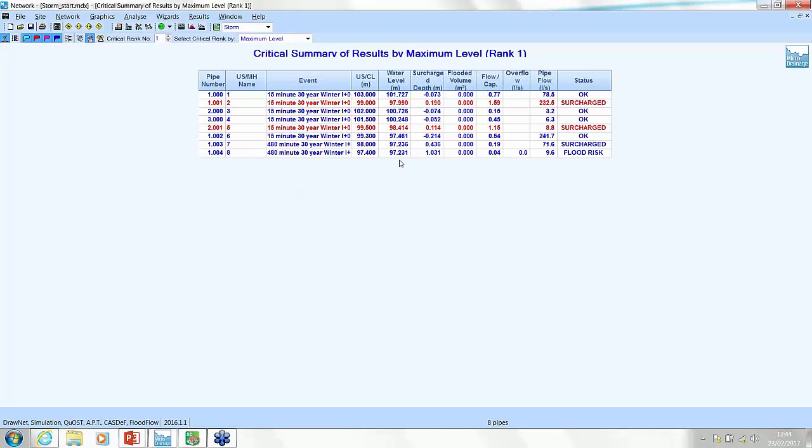So we're going to go with a tank that's 640 meters cubed, side slope of 1 in 4. We can see that the maximum discharge rate into our water course is not exceeded. We're at exactly 9.6 litres a second there. So we're all good. If we want to delve a bit deeper into those results, we can do.